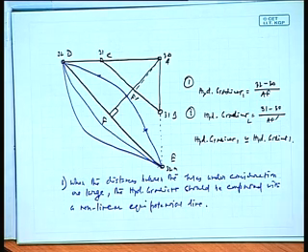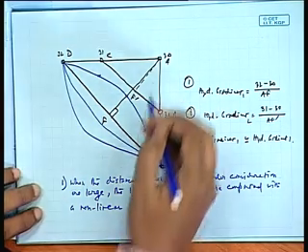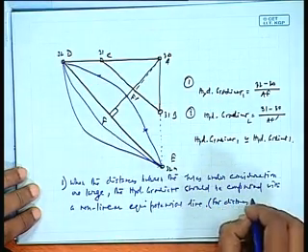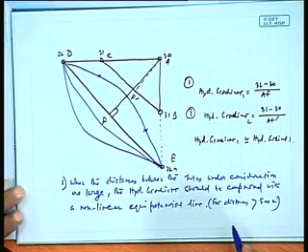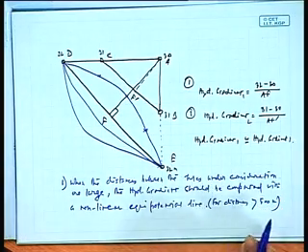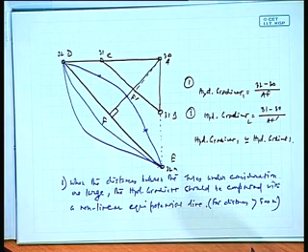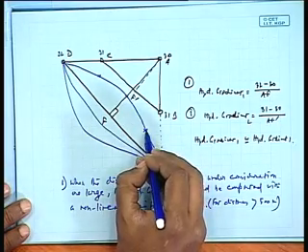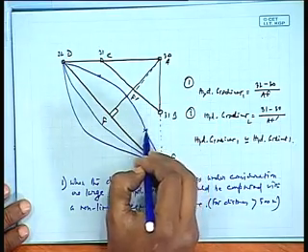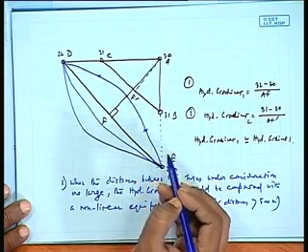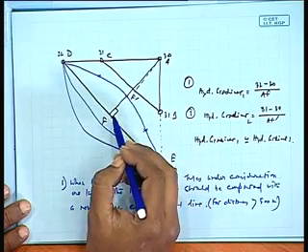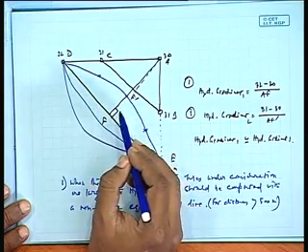For distances more than 500 meters from each borehole, we can say this is a non-linear equipotential line. We have to find the hydraulic gradient at all points, and from there compute the average hydraulic gradient, which would be used for the total field, the total groundwater body.